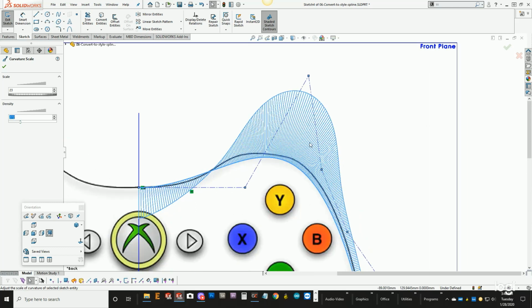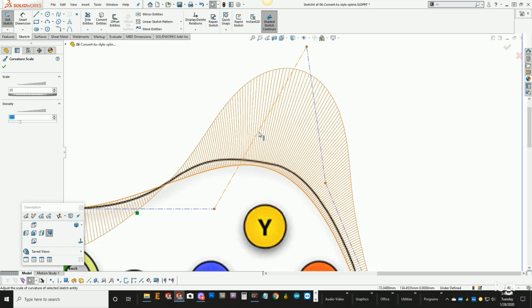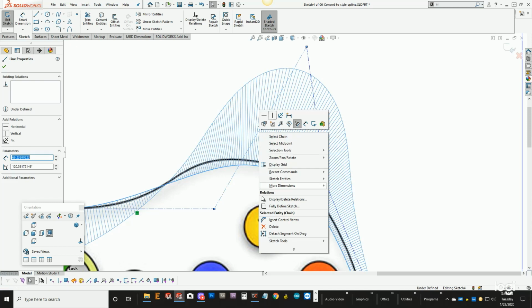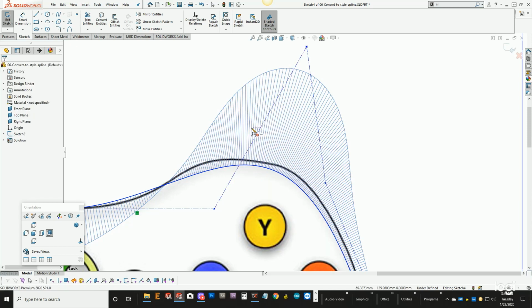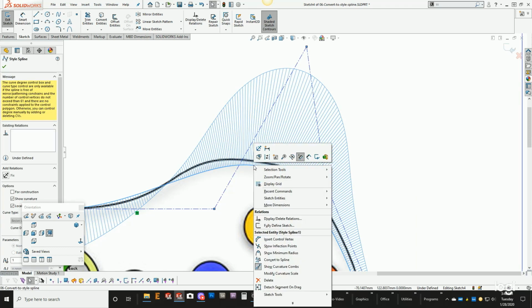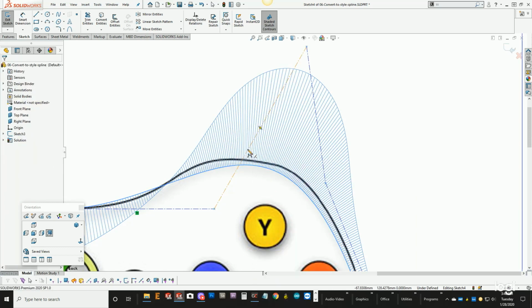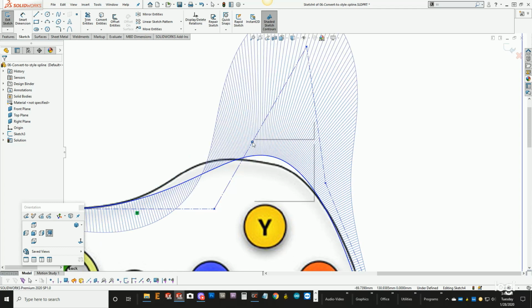And if you start to add more vertice points, polynomials, and let me do that right here. So the way you do that is right click, insert sketch control point, either on the cage or this original spline geometry. If it has a little circle with the slash through it, it means that you cannot place that point there, but I can right here.